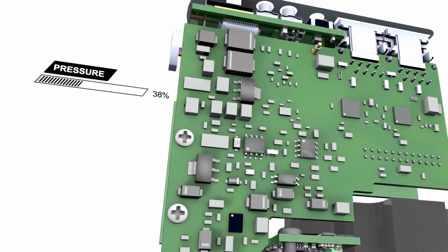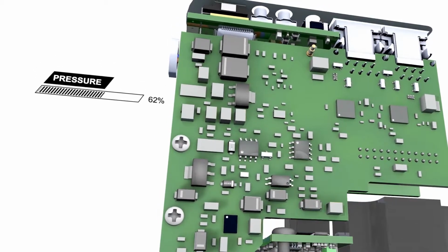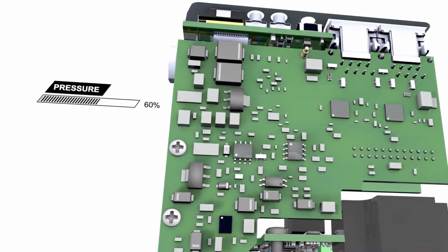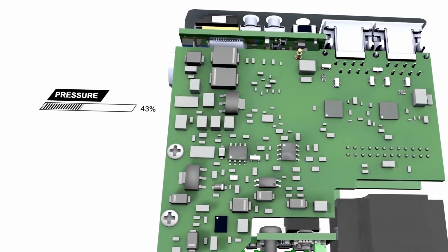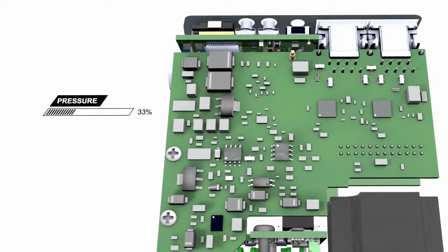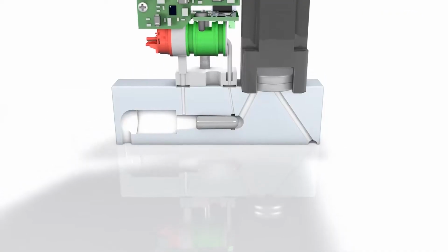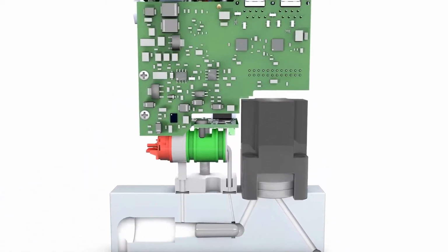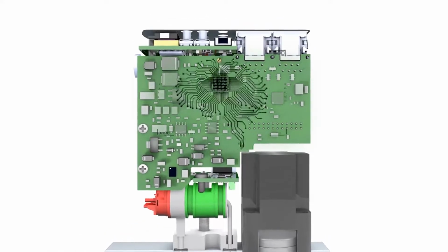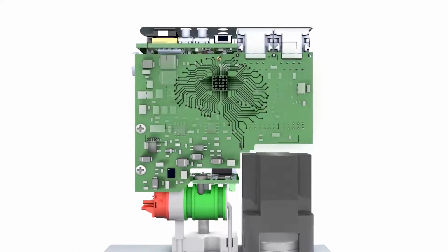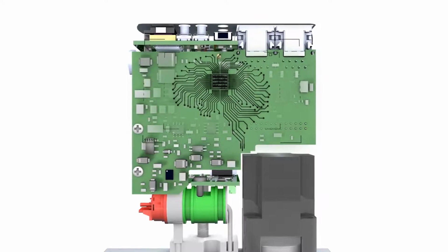The GP200 is constantly monitoring fluid property changes as a result of any temperature fluctuations and compensates for these changes in real time. Fluid properties are updated for temperature and pressure changes every 2 milliseconds to ensure process gas accuracy under real-world application conditions.